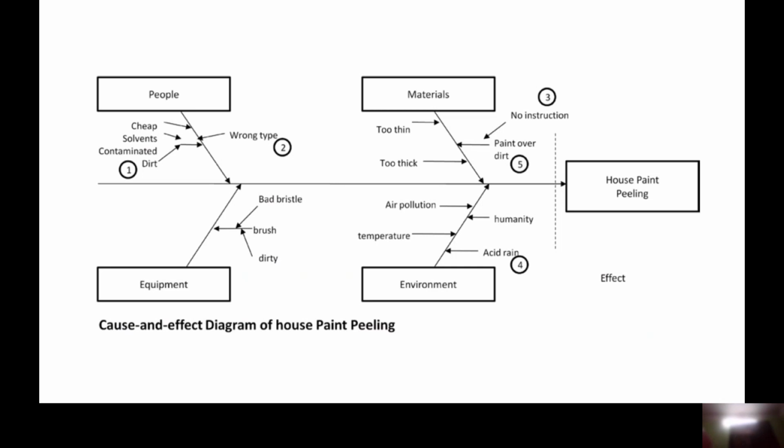Coating should not be very thin. But of course, there are some cases where coatings will be very thin, microns. Sometimes thicker coatings will be there, 2 mm, 3 mm and so on. So here the paint should not be too thin or too thick. That is only by experience. So these are the materials, and these are the two problems. The paint, with the solvent we are adding, should not be very thin. That is also quality. If it is very thin, that is when solvent is more and paint is less. That is a problem. If it is thick also, the peeling off problem will come.